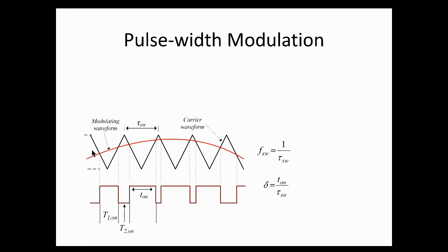So we then can connect that to some comparator, right? So if we look at it, if we have the modulating signal going below the carrier waveform, all right? So let's mark off our switching points. These are the points where switching takes place. At the comparator, we look at the two voltages, the carrier and the modulating waveform. Carrier is below in this region, as I can see, it goes to 0. Output of the comparator is 0.